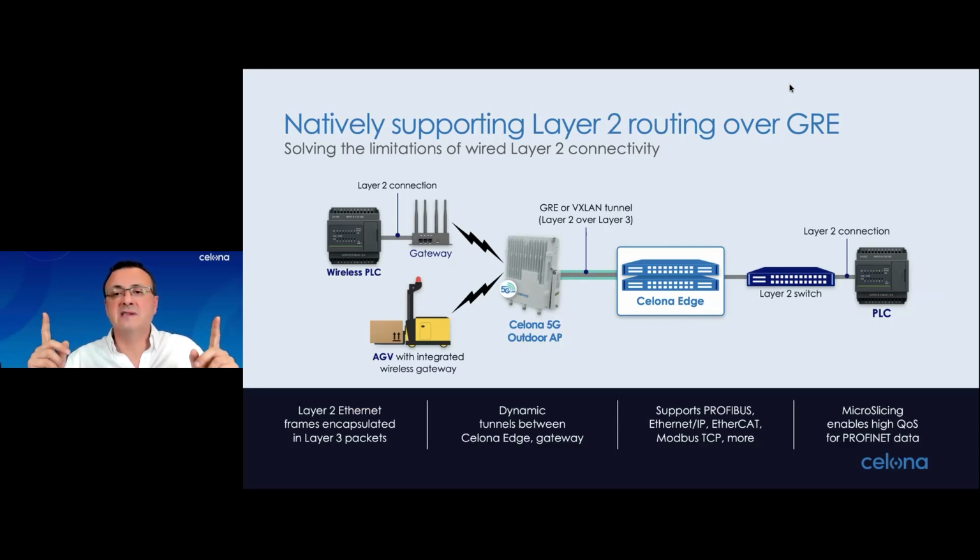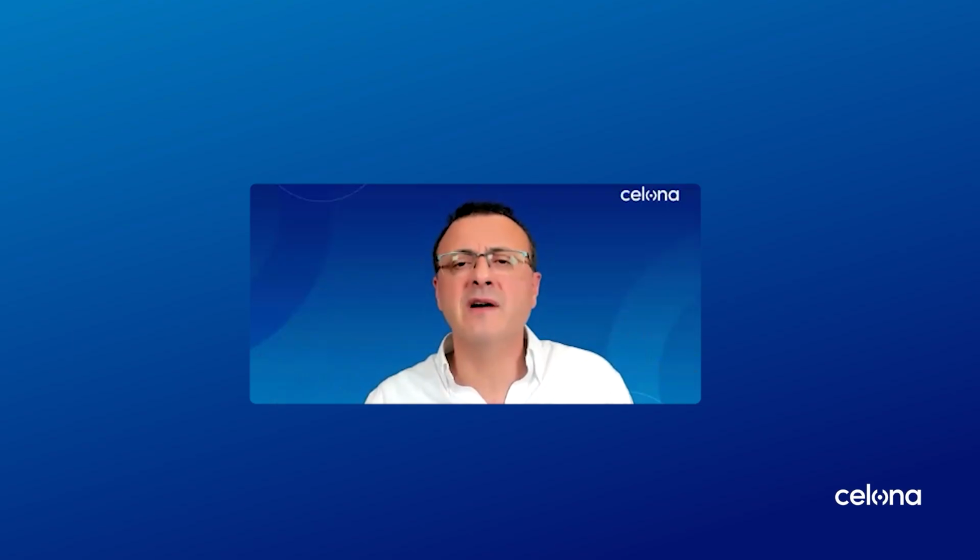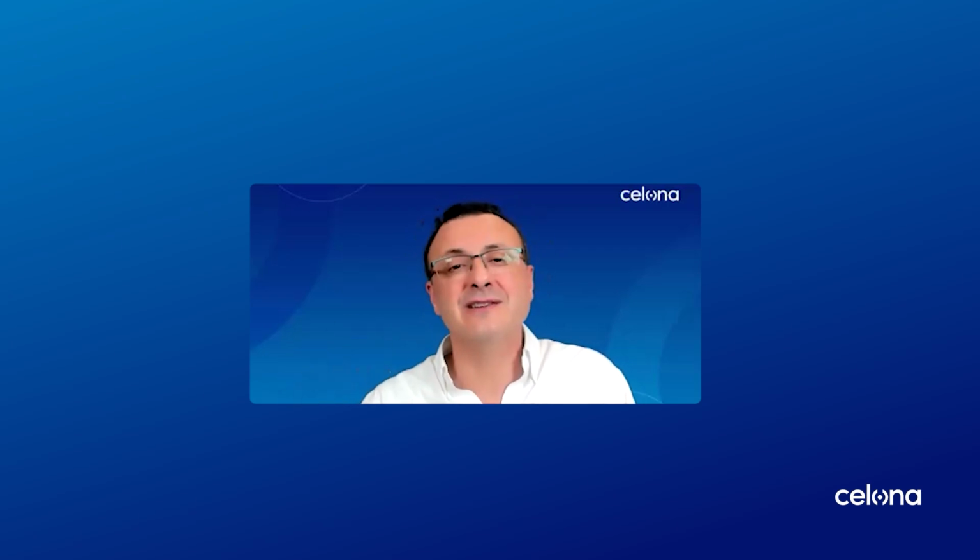And from the perspective of PLCs and controllers, nothing changes. Both ends, the PLCs on both sides, they still see a trusted transport layer. This is particularly powerful for mobile use cases like AGVs with integrated gateways, where you need to preserve this deterministic control behavior while allowing the endpoints to move freely. And because this runs over private 5G, we can combine it with microslicing and QoS enforcement and ensure that all the prioritization and quality requirements are met. The key point here is that we are not forcing OT systems to adapt to cellular. We are really adapting the cellular network to the realities of the industrial IoT system.